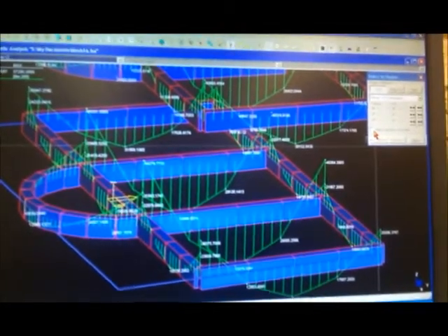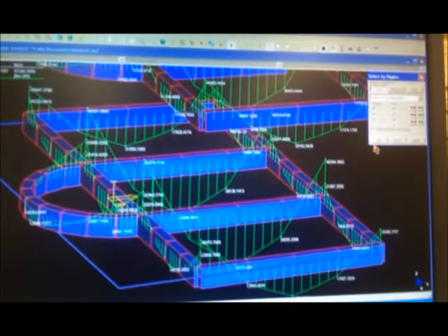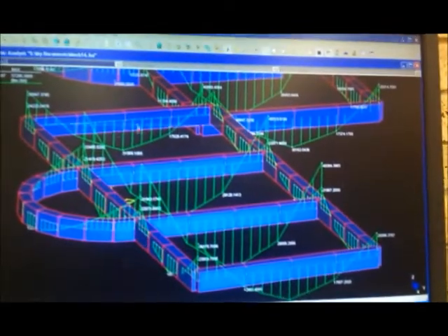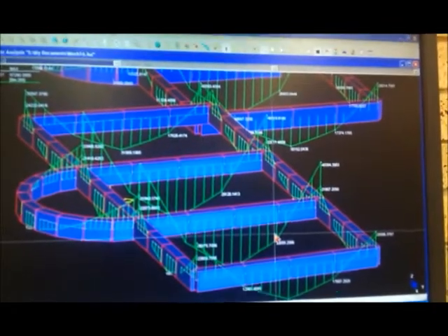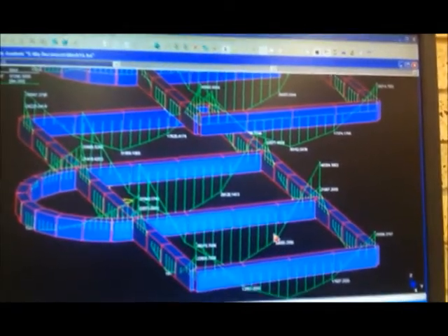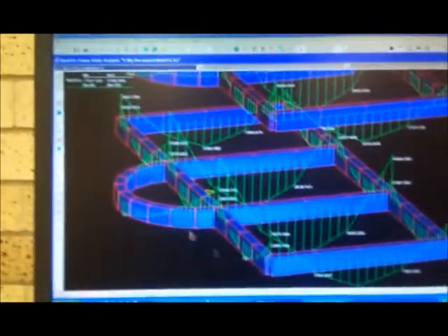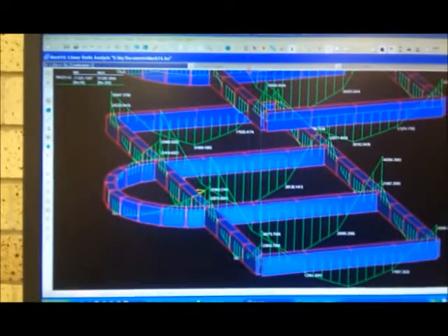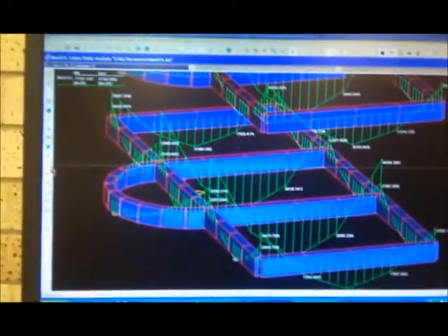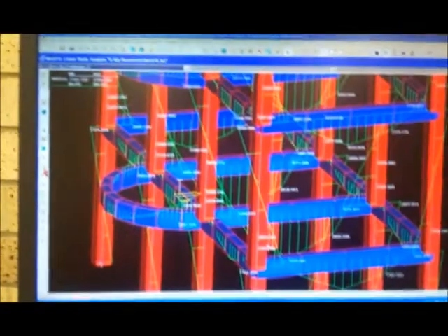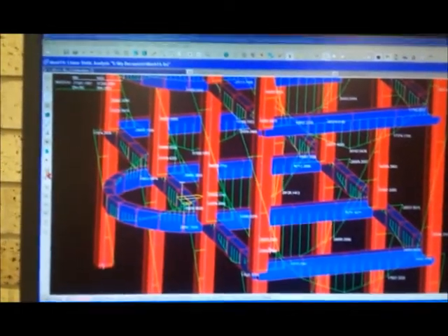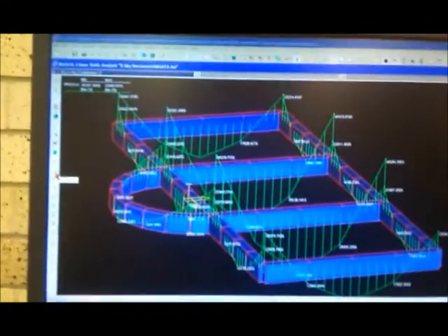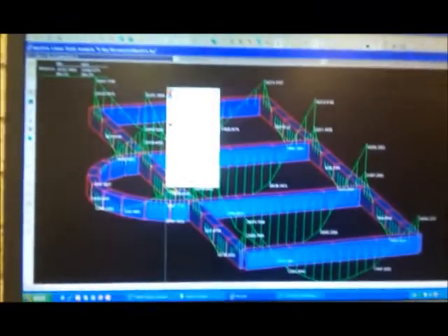I'll use this one, select partially selected, so if a beam is partially within this envelope, it will get selected. And I'll say OK. Now all of these beams are selected, right? I'll do Control A. By doing this, I've unselected these ones and selected everything else. What will I do now? Hide the selection. I'll go to this one. I'll press this one. It will put back the things that were hidden, and then I'll press on it again. You see, everything now is hidden except for this one.